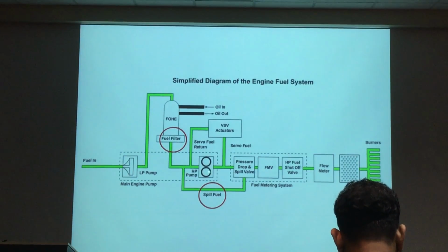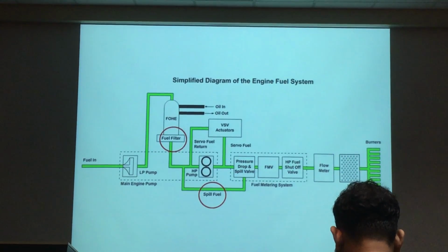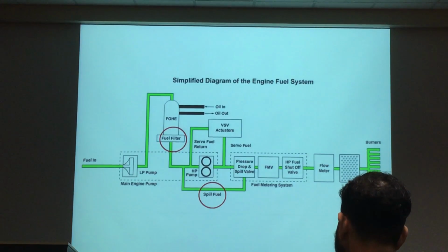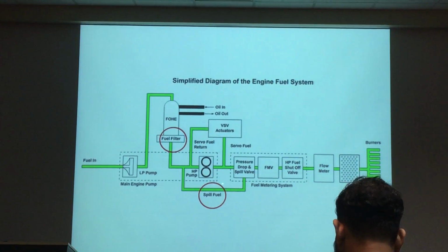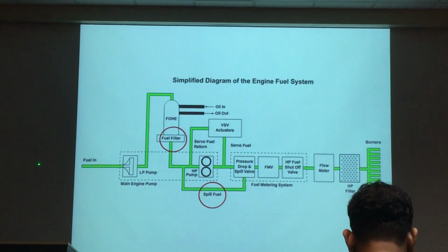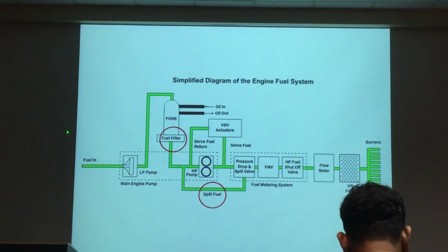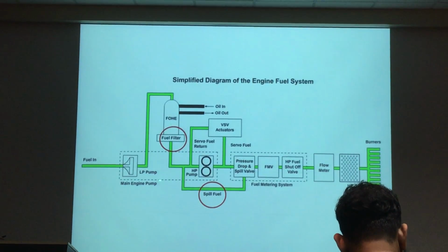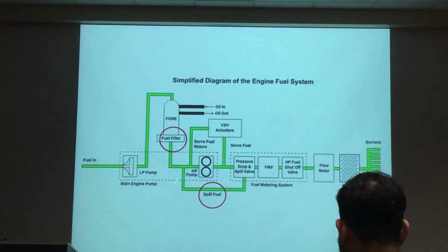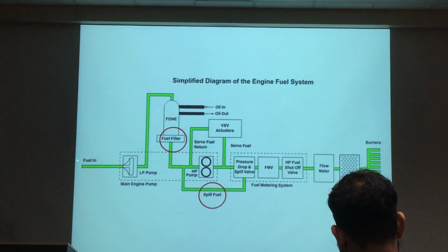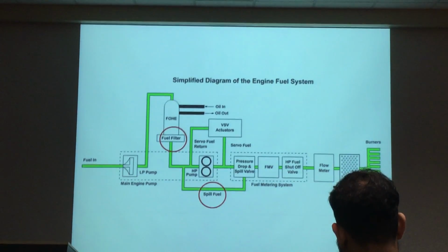Okay, during metering of fuel, they usually over-design a bit. The fuel flow is more than the requirement. Because of this, there's some spill over. Or sometimes you have a bit of back pressure that needs to be released. All this will dump back to where? To the pump inlet. They do not dump it all the way back to the fuel tank. If they dump all the way back to the fuel tank, you revert back to zero pressure. That wastes pipeline and pressure energy. You dump here faster. For example, here is 500 psi, and when you dump here you only drop to 200 psi. Then you pump again straight away. You become more efficient, correct? If you dump back to the tank, you go back to zero and pump again. From 0 to 500, you need more energy. So energy is wasted.